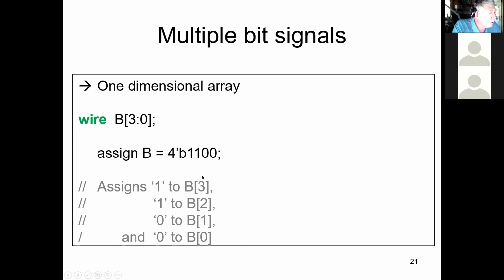And then we also have one other strange convention, and that's the way we write constants. We'll talk about this in a couple of lectures later on, because constants can be really, really confusing. But if you keep them simple, they're fine. The way this works is you put a number, which is the number of bits, not the number of digits, but the number of bits. And then you put a tick mark, apostrophe, and then you put the base. You're going to use binary, hex, or decimal.